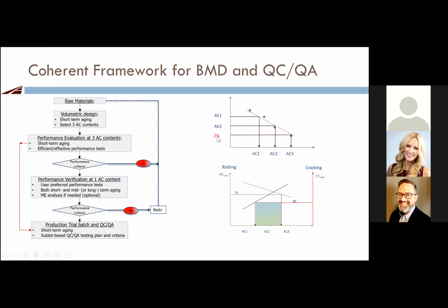We're really talking about the lowest air void, or the highest density, 98%. We really don't want to go lower than 2% air void, or denser than 98% density. Beyond 98% density, you potentially cause not just a rutting issue, you potentially cause a bleeding issue. So 2% air void is the upper limit, giving me the optimum upper limit for asphalt content. I don't want to go beyond that.